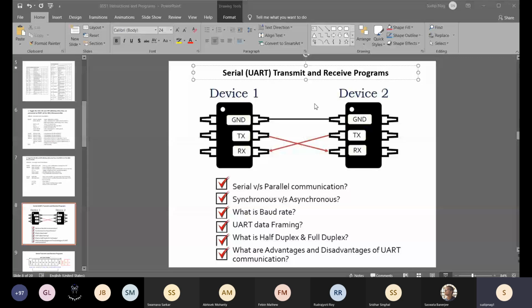Output TX from the second microcontroller is connected to the RX input of the first microcontroller. This crisscross connection is important for UART, and this is a dedicated hardware connection. That means there are physical wires, or some sort of conductive path between the lines, as shown here.